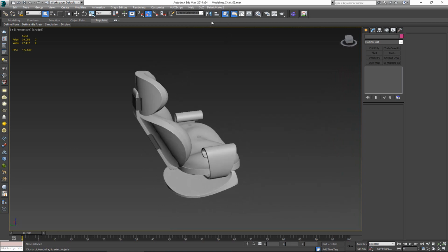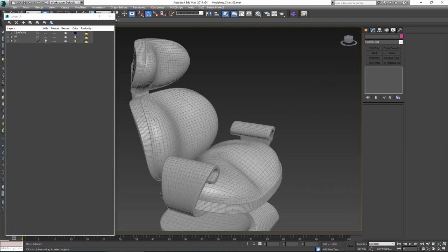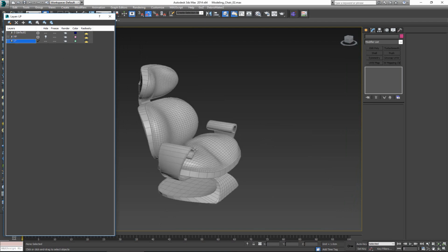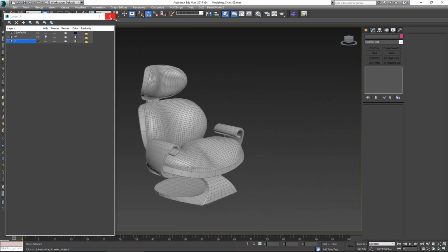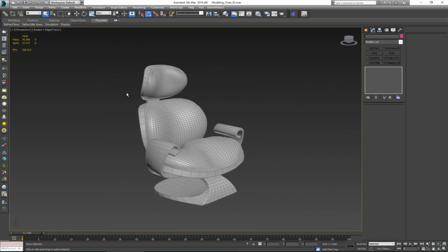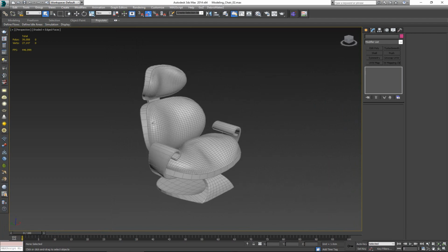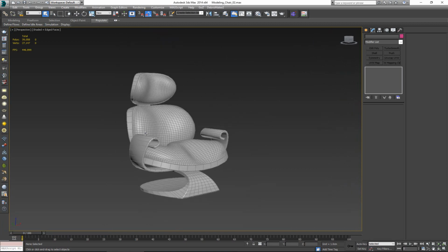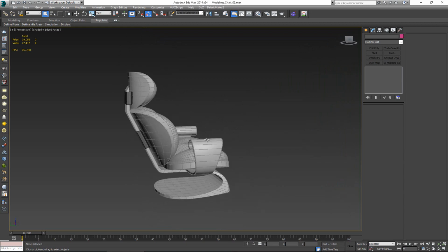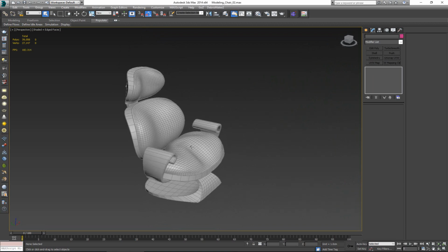So far, what we have created is basically a low poly model and a high poly. What we're seeing here is the high poly model, and this thing here is a simplified version, or the low poly. If we want to add in more textures later on in Unreal, we would like to have this thing unwrapped. Now, I will do the unwrapping here in 3ds Max, which I do want to stress is not my favorite way of doing it, but I want to show you guys how you can do it in Max so you don't have to use an external software for it.